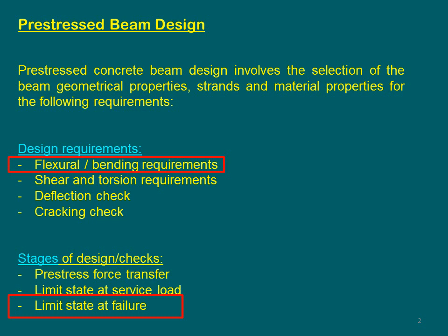If you like, you can call it the capacity point, because we understand that concrete is going to be surviving after this strain. This strain at 0.003 is just a stress-strain value that the code would like you to consider for the concrete and not to allow the concrete to go beyond this amount of strain.